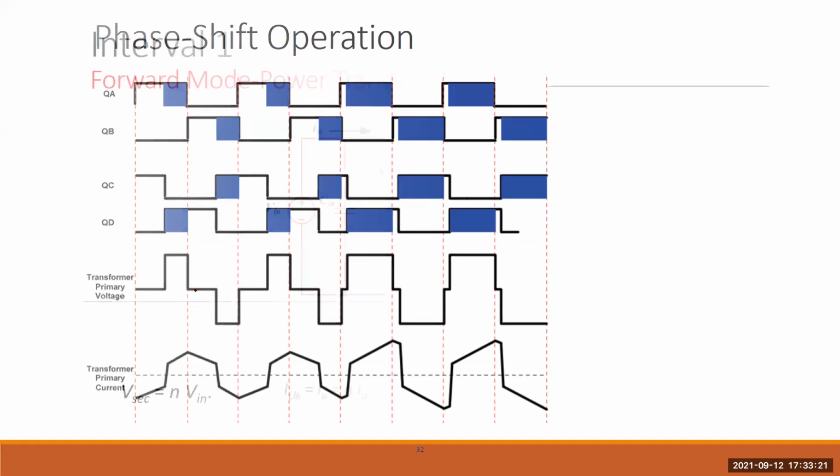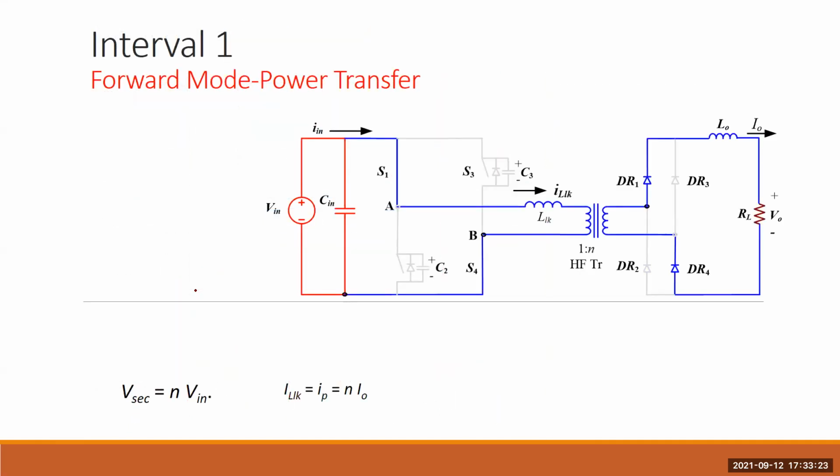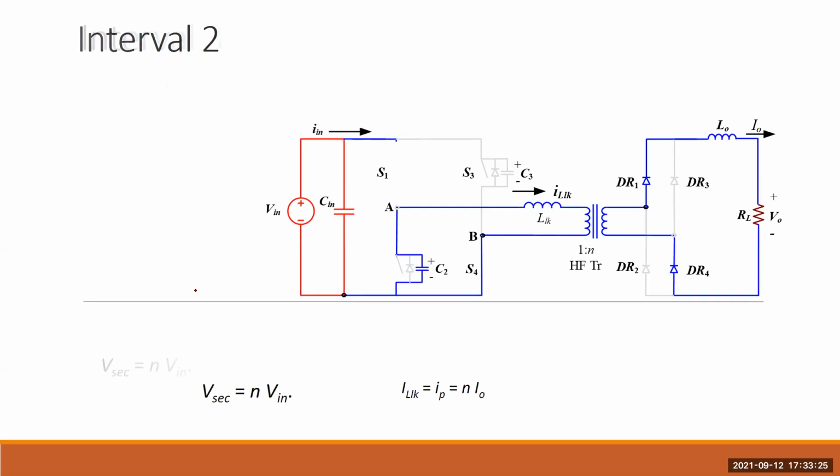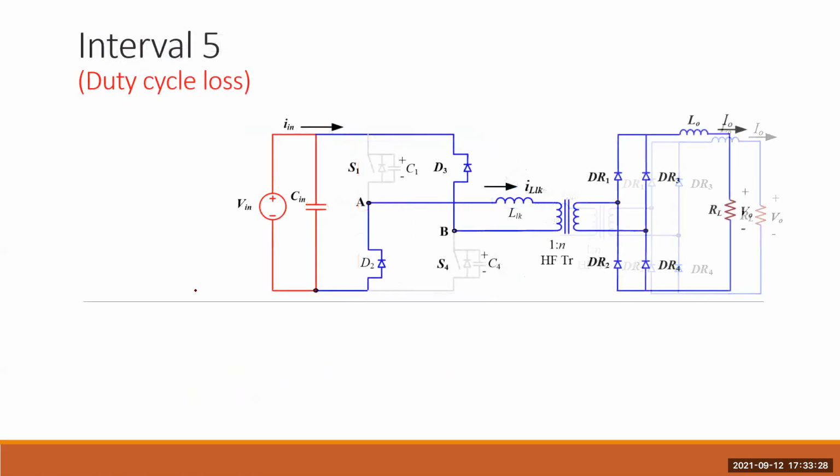No, backflow power is there, and that's why this modulation is still efficient, because for some time the power is flowing back, so you can see energy recovery. Power flows back to the source basically. So you are saving energy during this time, as well as reducing the switching losses.